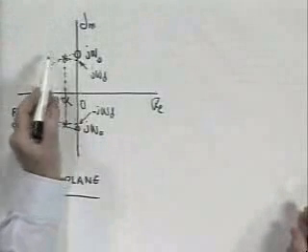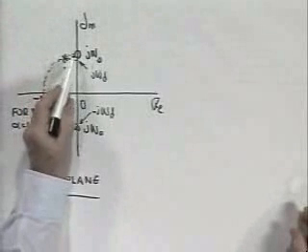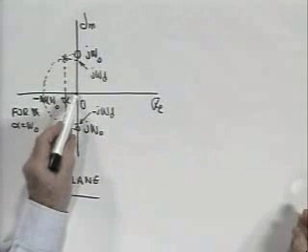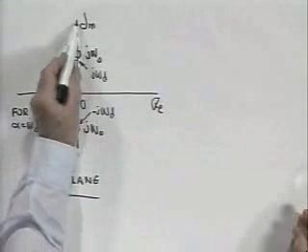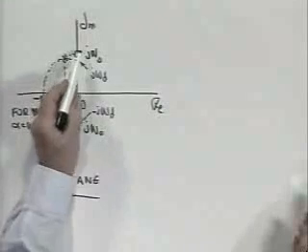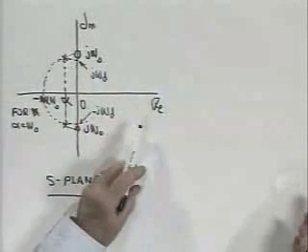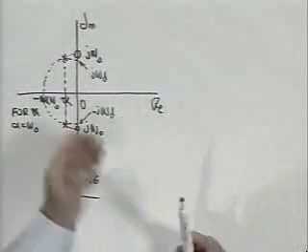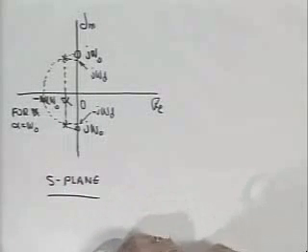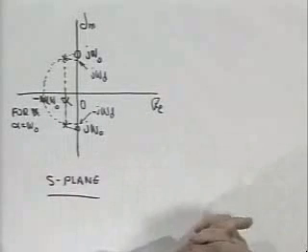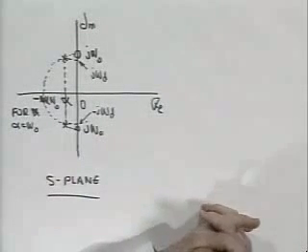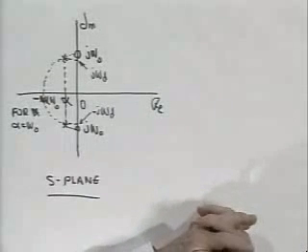In the vicinity of the zero, the fact that it's pushed up very high near the zero means that this decline from a value of 1 to close to 0 and then back up to a value of 1 occurs very sharply. And the closer the pole is to the zero, the sharper that transition either side of the zero will be. So by looking at the S-plane diagram for the circuit, you can get a sense of how the magnitude of the transfer function must behave without writing it out and doing the complex arithmetic and plotting magnitude and angle.